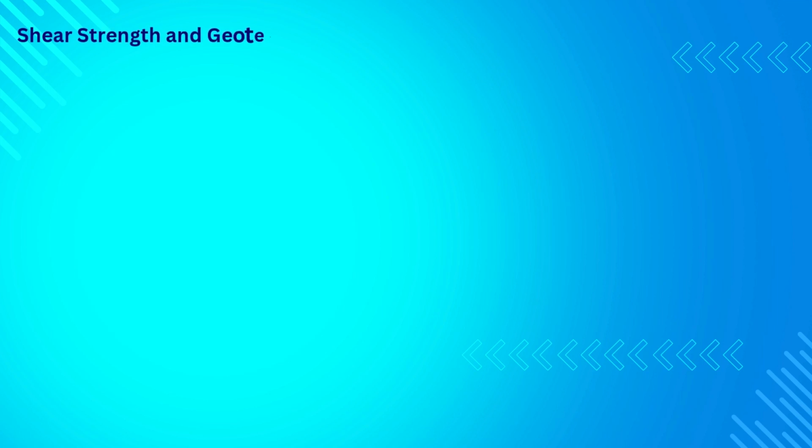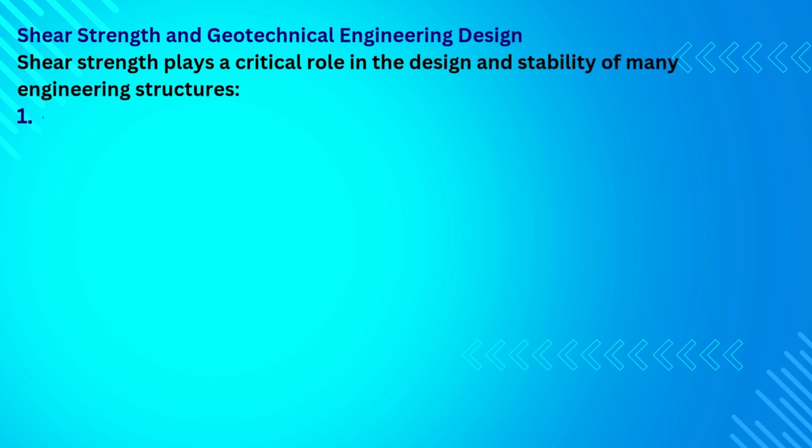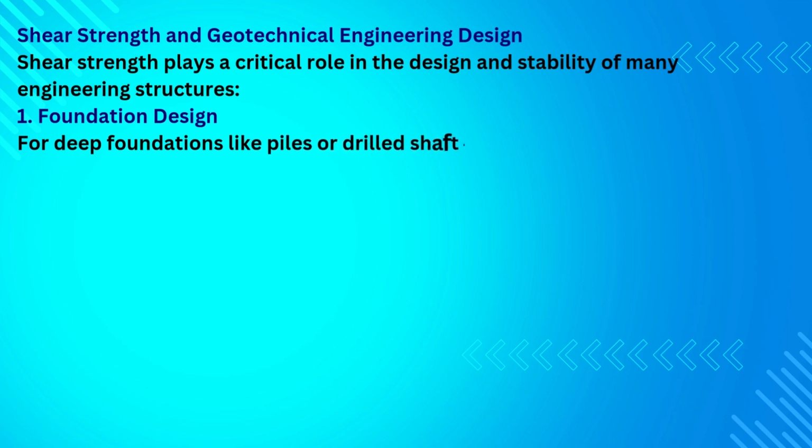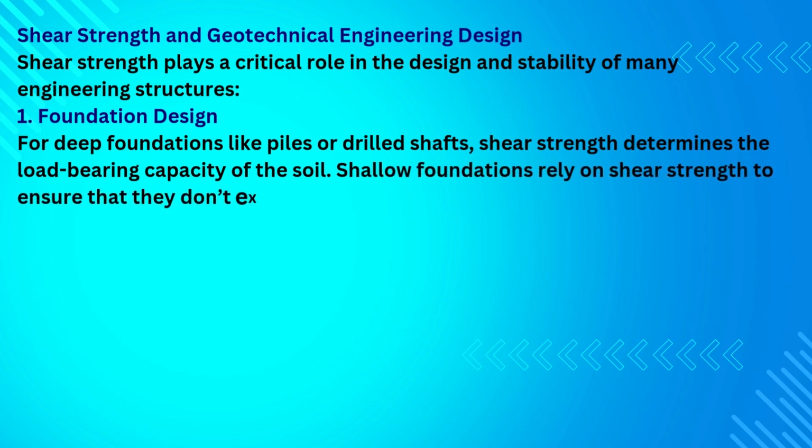Shear strength and geotechnical engineering design. Shear strength plays a critical role in the design and stability of many engineering structures. 1. Foundation design. For deep foundations like piles or drilled shafts, shear strength determines the load-bearing capacity of the soil. Shallow foundations rely on shear strength to ensure that they don't experience excessive settlement or failure.